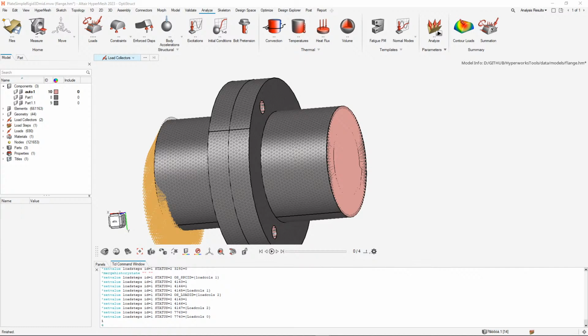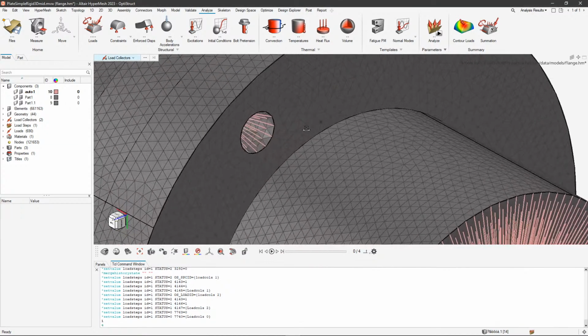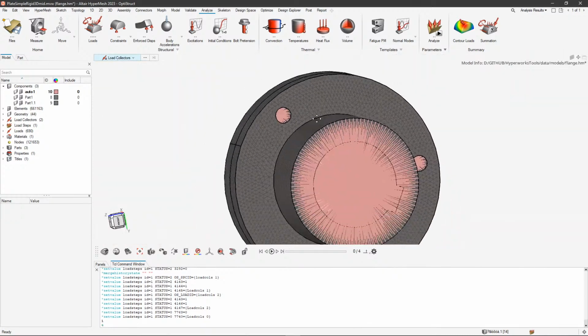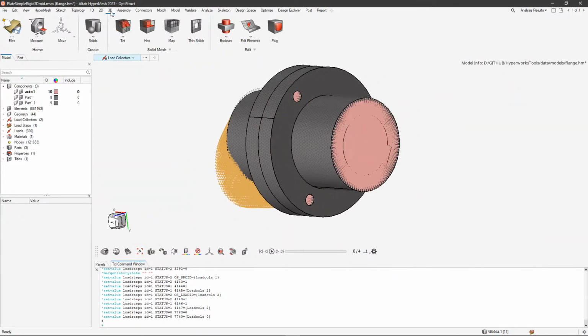I did not set up the MPC forces to being outputted, and we have programming errors during element quality check. Ooh. Yeah, that's not good. But where could it be that you have such a bad element? Let's check that simply quickly.